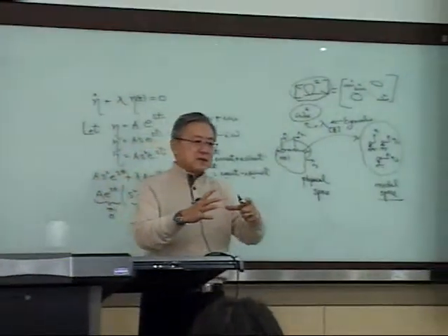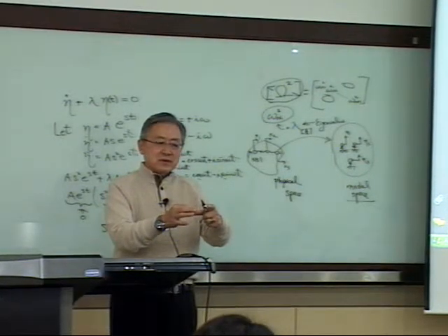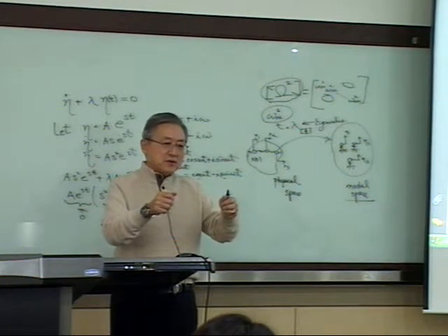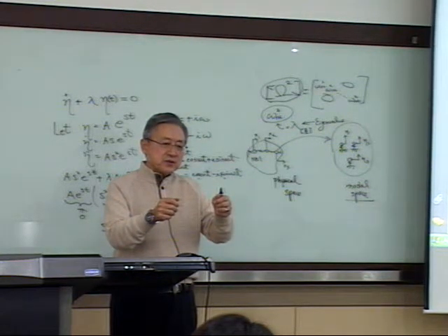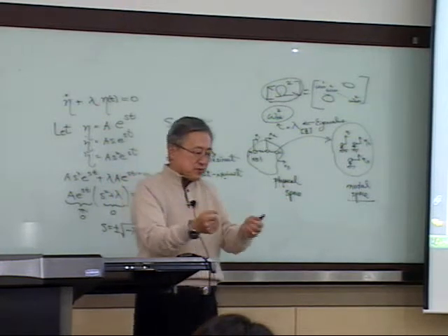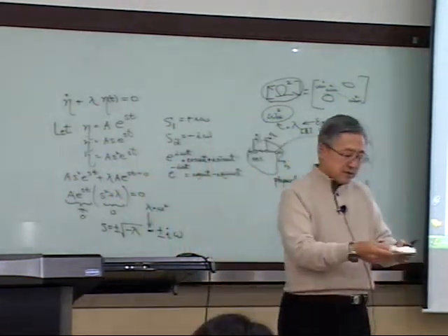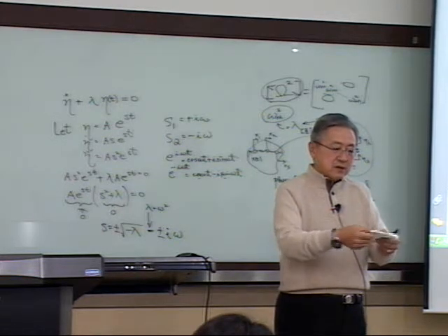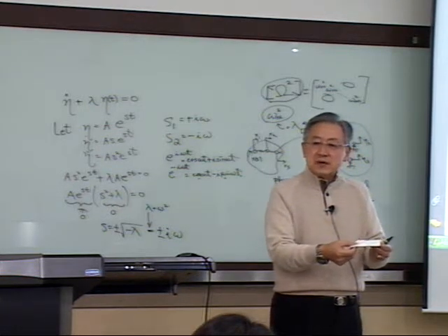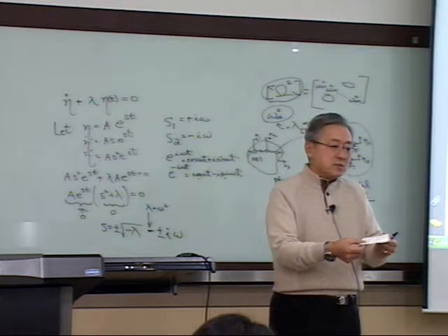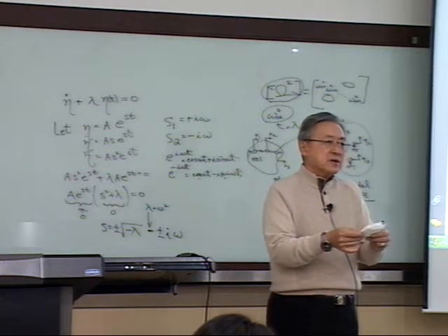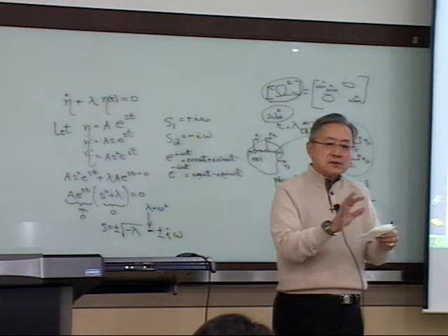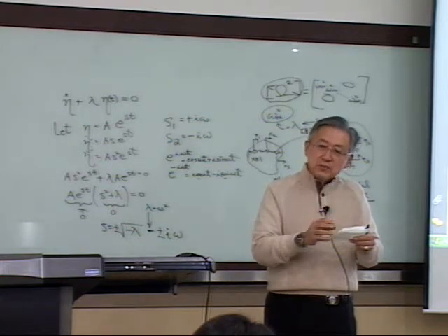For example, you have a CD with a hole at the center. If you look at the mode shapes and the corresponding natural frequency, whether you put this guy this way or this way, the frequencies are the same and the mode shape is the same. So in some situations, the natural frequency could be the same between two modes.